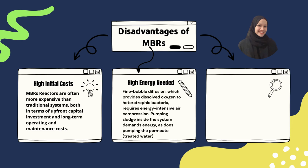Secondly, high energy needed. Several factors contribute to the MBR system's relatively high energy demand. Fine bubble diffusion, which provides dissolved oxygen to heterotrophic bacteria, requires energy-intensive air compression. Pumping sludge inside the system demands energy, as does pumping the treated water, heating and pumping for backflush and cleaning chemicals, as well as the operation of process control equipment and instruments, all of which increase energy expense.